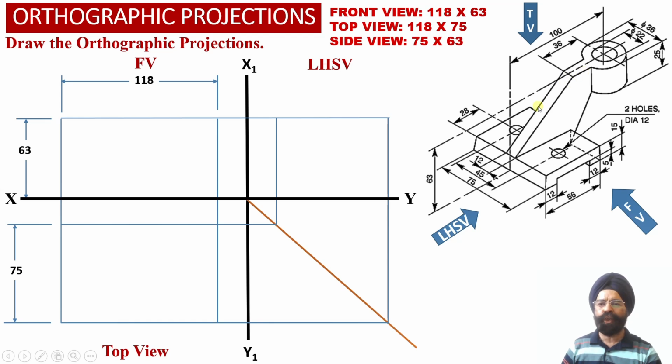Then we have element number 2, which is an inclined vertical web, and this inclined vertical web rests centrally on top of this horizontal surface over here, and this web happens to be parallel to the front face of the solid. Then here we have a hollow cylindrical element over here, which is going to be our element number 3. Let us proceed to evaluate different elements of this engineering object alongside the width of the solid. So now we can check.